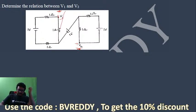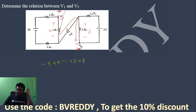So we are applying KVL in this loop. Can we apply KVL in this loop? Tell me. If we apply KVL in this loop, we get minus V1, and we don't know the voltage here. Let us call this voltage X, and this voltage Y. Minus V1, plus X, then minus 1, then plus Y, and then plus V2 equal to 0.